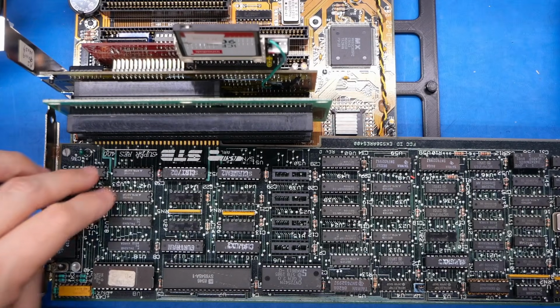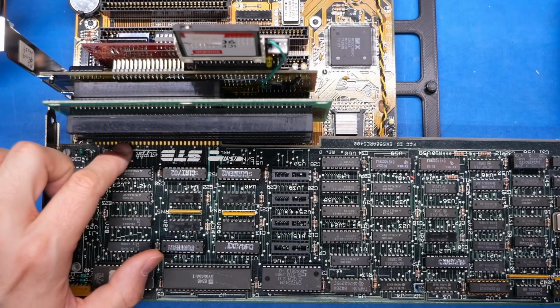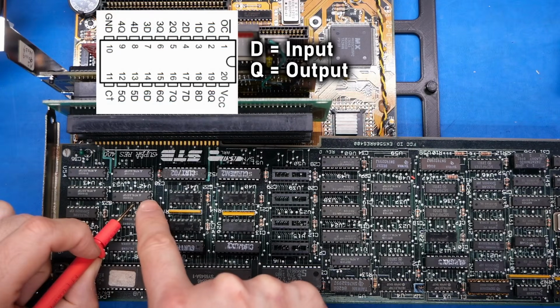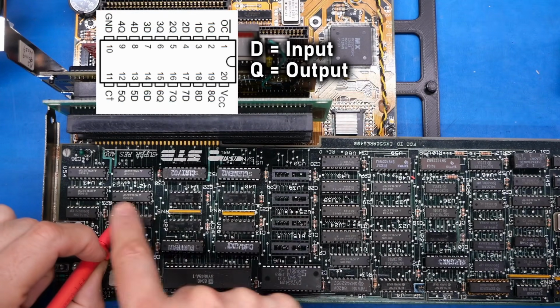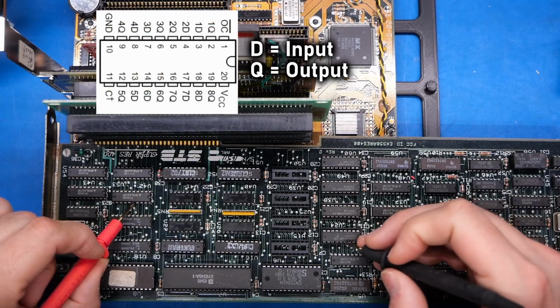Okay, so I have a feeling with these flip-flops, we might be dealing with one set of these that talks to the 8-bit ISA bus, and the other one is going to be handling the attributes and the character. That's my guess, at least. So we're on pin 16 on this chip. I just looked it up on the data sheet. That's an output, so that's going to the DRAM as an output. So this is loading data into here. It's not for reading, so that's obviously not going to be our issue.